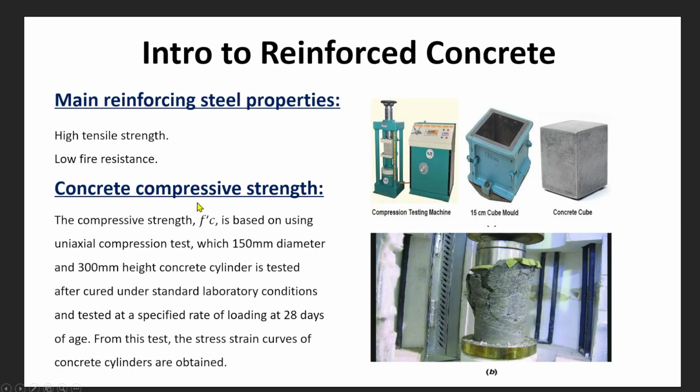The main reinforcing steel properties are high tensile strength, as said, and they are low in fire resistance. Why do we add reinforcement or steel bars? Because they are good in tensile strength. Concrete doesn't have the ability to resist tensile stresses, but it is good in compression.